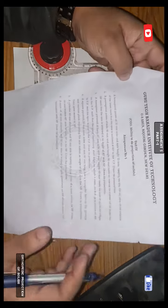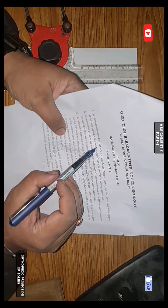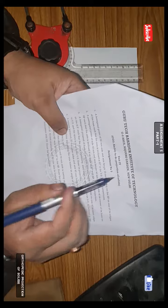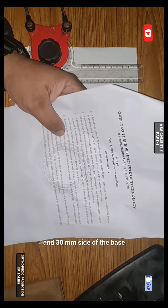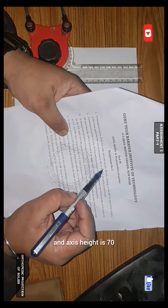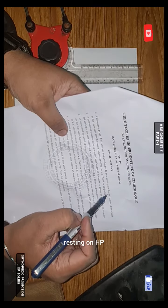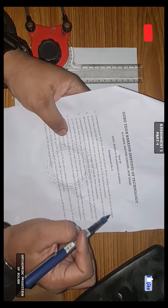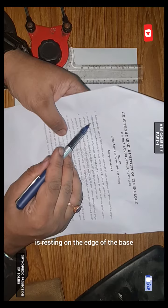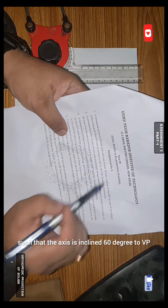So first of all, it is saying that the hexagonal prism is having 30 mm side of the base and axis height is 70 mm, resting on HP on one of its edges of the base. Hexagonal prism is resting on the edge of the base such that the axis is inclined 60 degrees to VP.